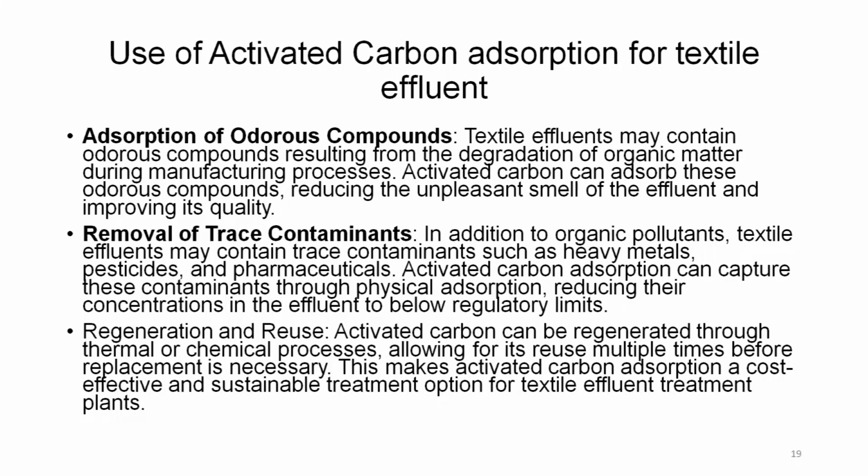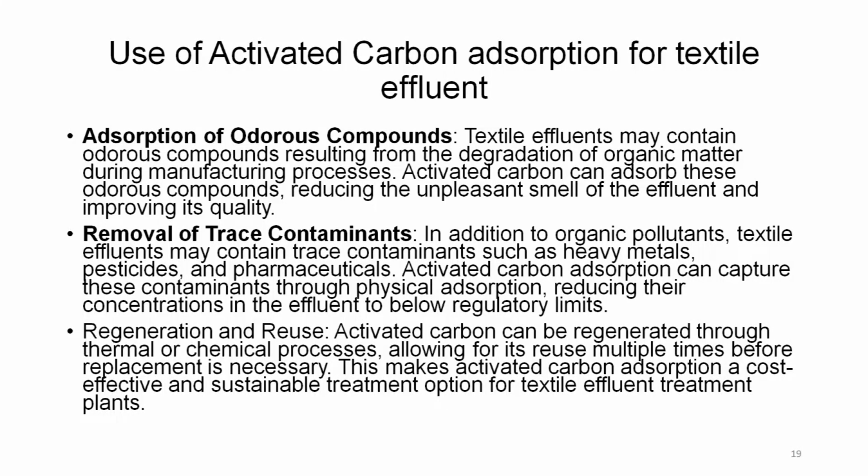Adsorption of odorous compounds. Sometimes the textile effluents are very foul smelling. So, they are because of certain bacteria, and pathogenic bacteria could also be present there. Textile effluent may contain odorous compounds resulting from the degradation of organic matter during manufacturing processes. Activated carbon can adsorb these odorous compounds, reducing the unpleasant smell of the effluent and improving its quality.